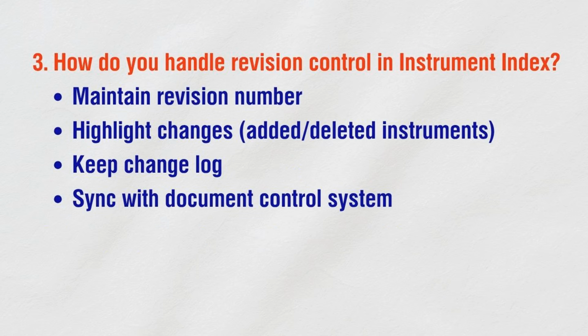How do you handle revision control in instrument index? Maintain revision number. Highlight changes, added, deleted instruments. Keep change log. Sync with document control system.